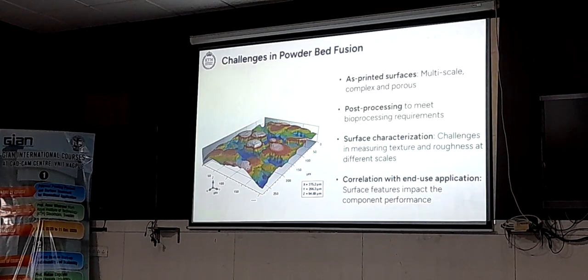So are there any other preventive measures that we can take to increase the shelf life? I mean, not without changing the polymer. Of course, you can have less degradable polymers. And I will also show tomorrow that, depending on which temperature you store your polymer at, it will also influence the surface roughness. So that's also important, not only the shelf life itself, but also which temperature. Normally you can say we keep it in a cold environment because then it degrades more slowly, but then you can also influence the surface roughness.